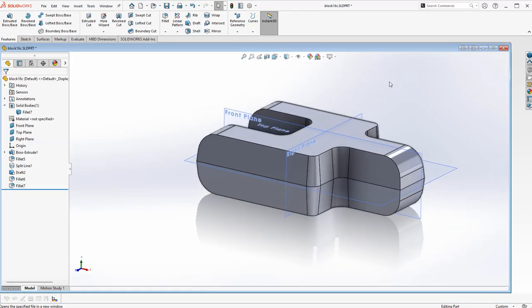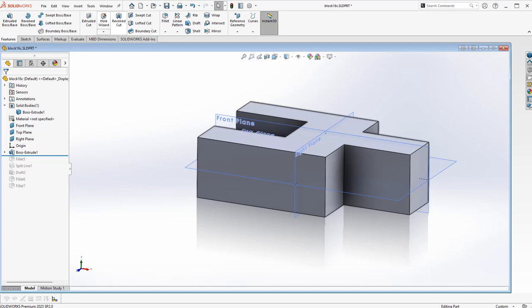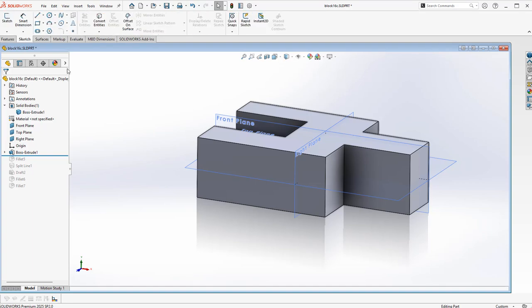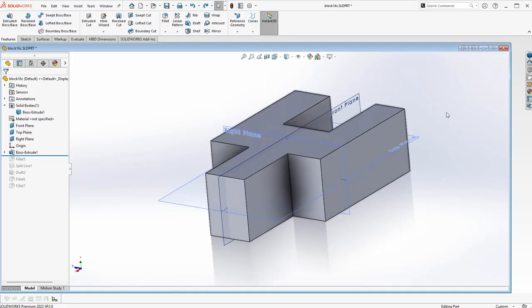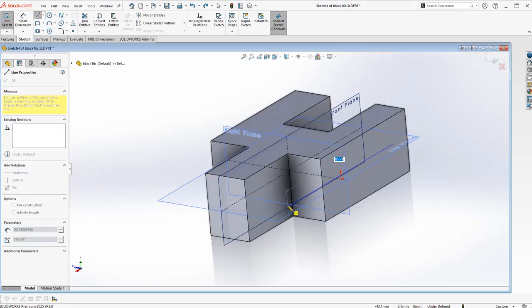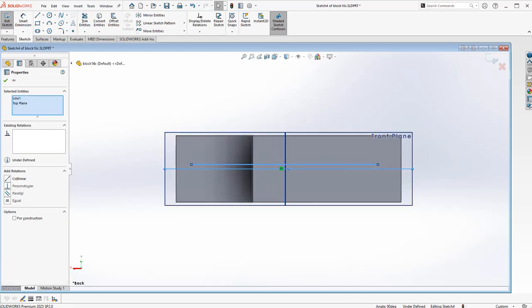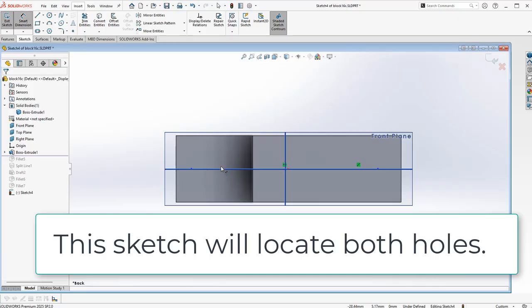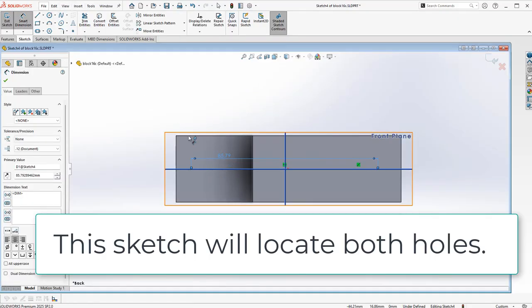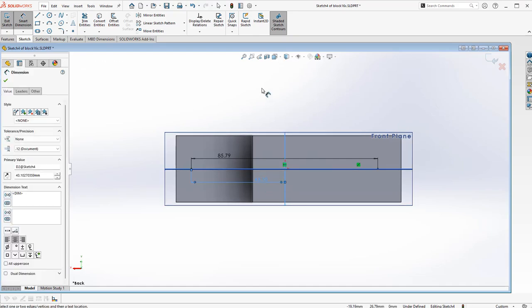So of course, a more effective method might have been to establish my pivots early on in the design. That makes really good sense. So, the sketch that I established at the same time. All right, so I have to reestablish that. I hit the space bar, square up on the sketch, look straight down upon it, establish my dimensions as necessary. Now, if I'd have done this early on and assembled everything off this geometry, then I wouldn't be dealing with failures in the assembly, see?